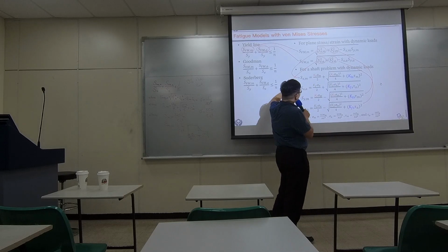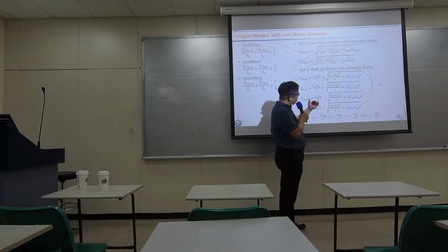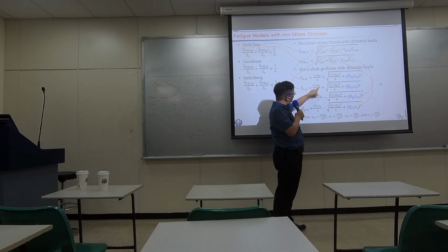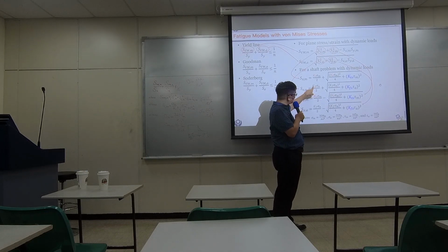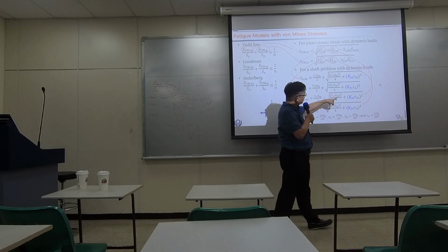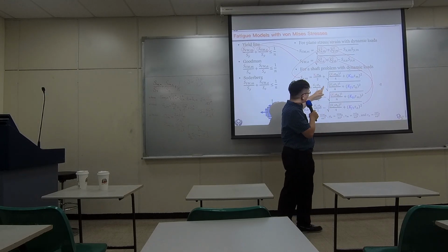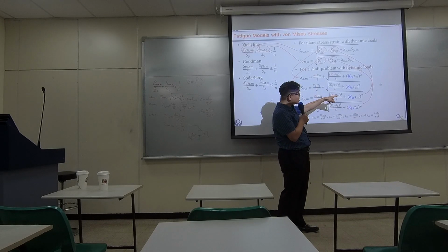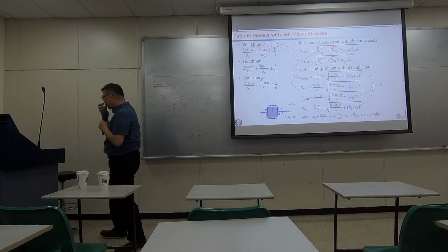However, the amplitude represents the dynamic part of the stress. So for sigma amplitude, we use the dynamic K. This is the dynamic load and normal load. This is the dynamic load and shearing. So here's where we can apply KF and KFS. How do we get KF and KFS? Use the Q and QS. So this is how everything becomes so messy.